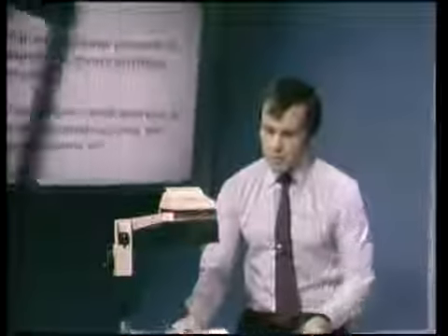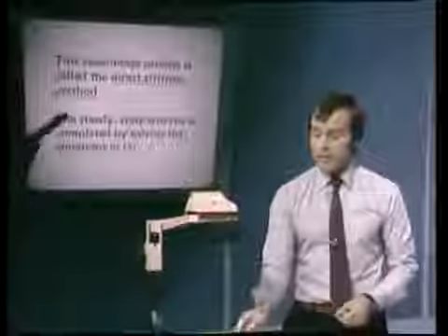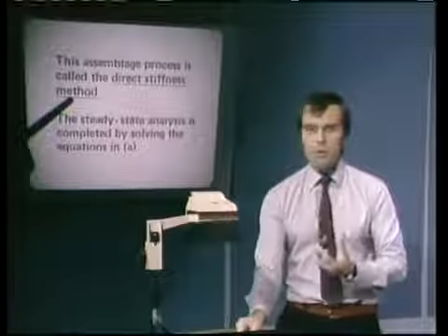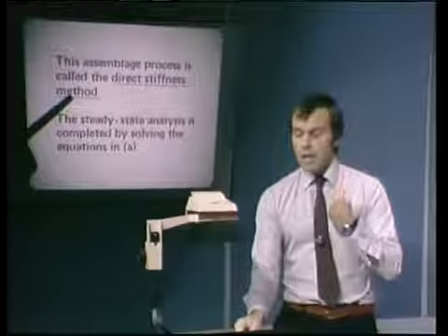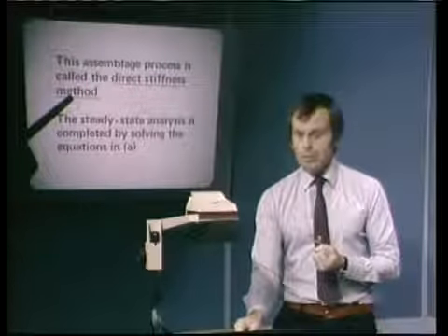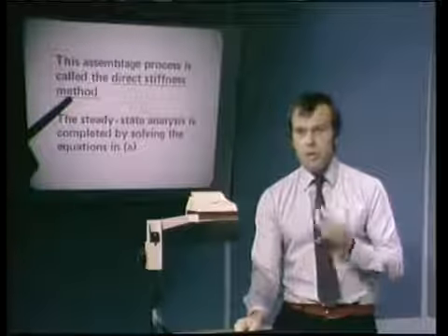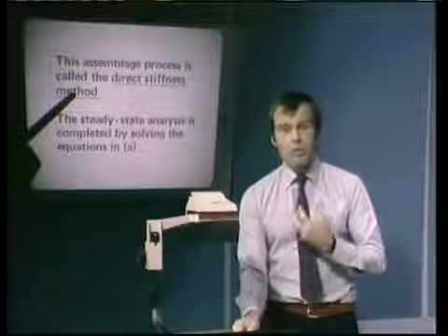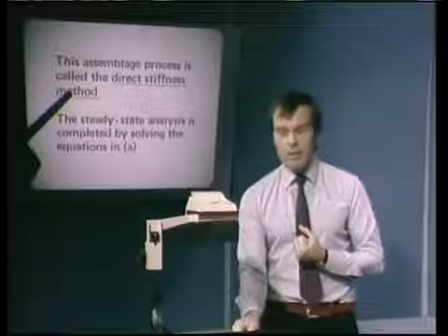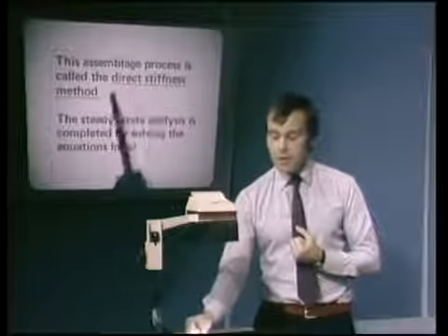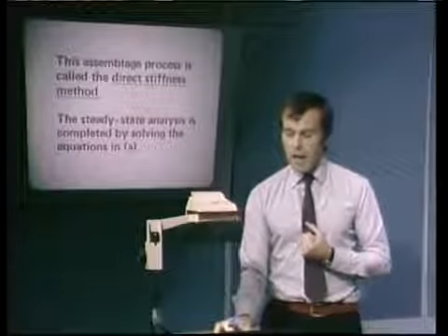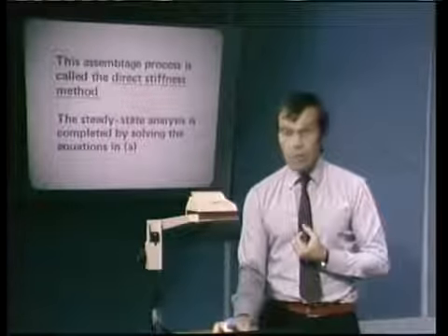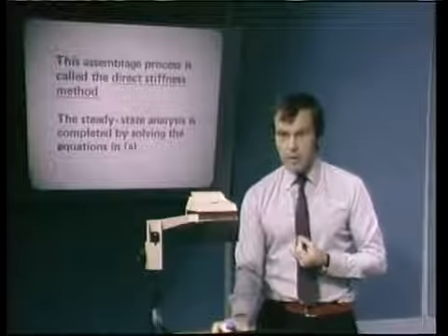This assemblage process is called the direct stiffness method, an extremely important concept that is very well implemented in a computer program. It represents the basis of the implementation of the finite element method in almost every code that is currently in use. The direct stiffness method also has a very nice physical explanation, and this is what I really want to talk to you about now for the next 5 minutes.